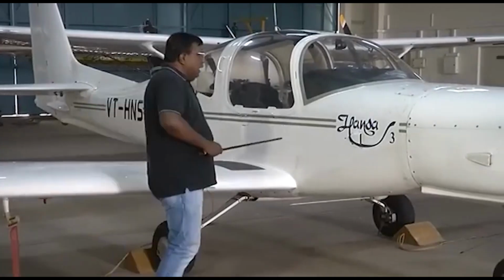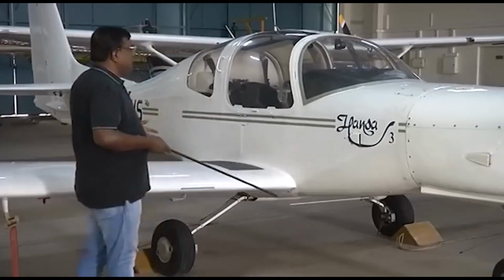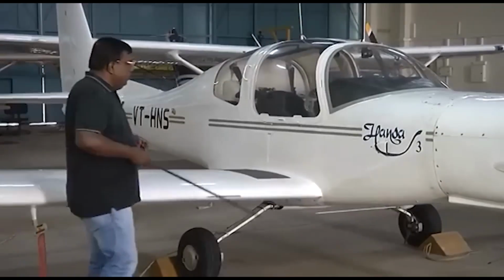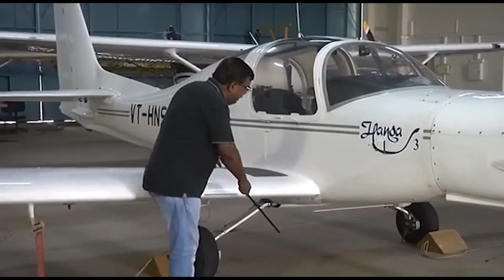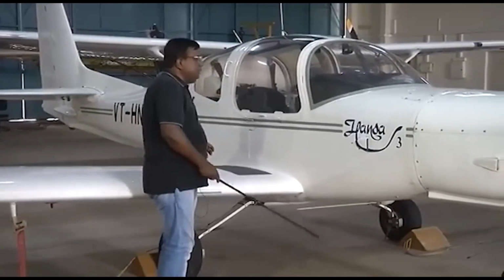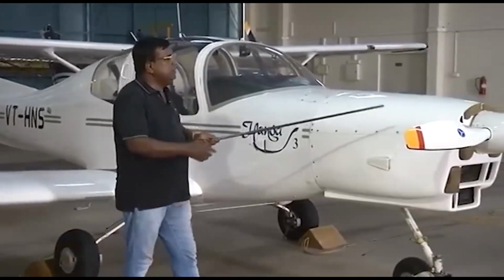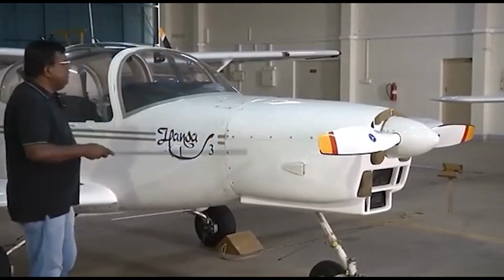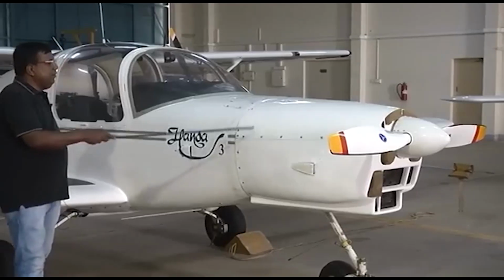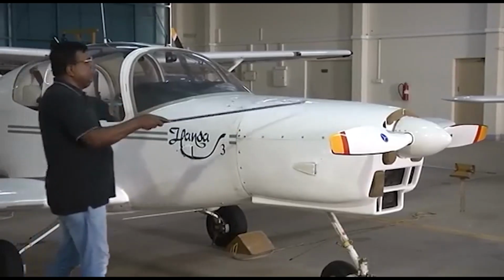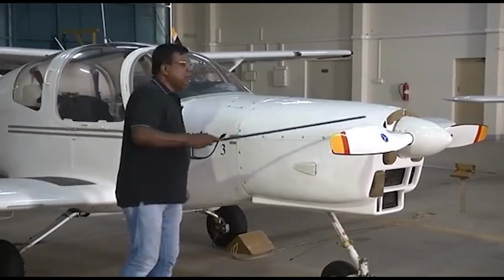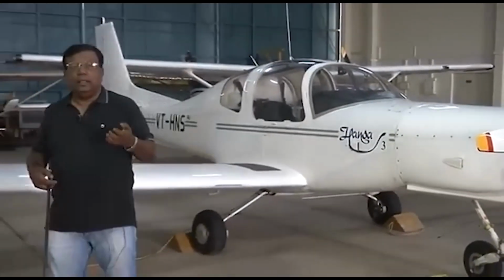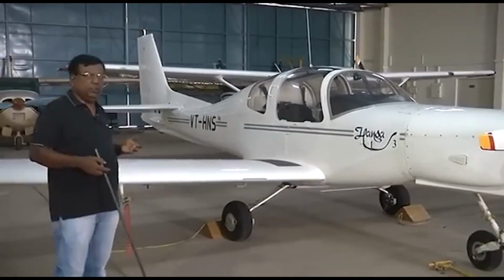And second part, how do I distribute the mass so that the CG is at the point where I want? One is, okay, I have seen the landing gear, so I'll put it a little ahead of the landing gear. Second thing you see here, this is the thrust line, okay? If the vertical CG is very far away from the thrust line, then this thrust will be giving a moment about the CG, and the pilot will have to make some corrections before he goes for a flight.